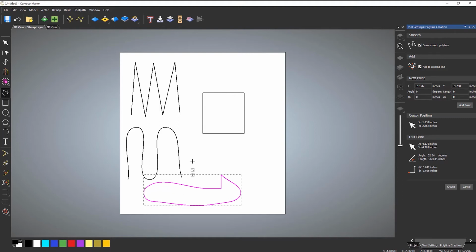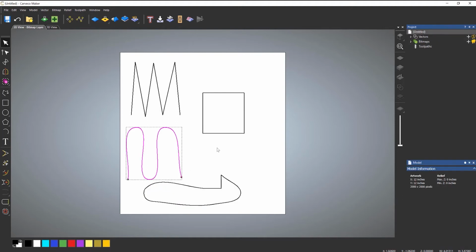If it wasn't joined up, it would look like that. So I would have a green dot on the left hand side, and I've got a red dot on the right hand side. So that denotes the start and the end. So a little tip, if something isn't joined up, you'll see that you'll have a green, and you'll definitely have a red dot. So keep an eye out for those red dots. A lot of the time when you're machining, you don't want to have those. Okay, it means that something's not closed.